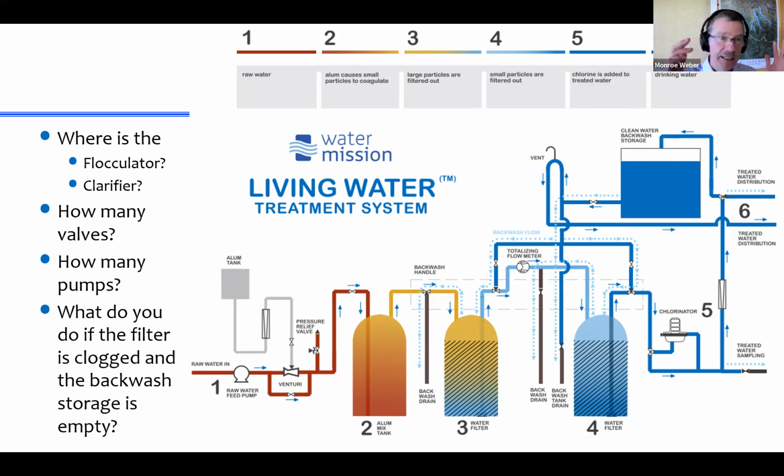It enters the entrance tank. It goes through the LFOM, into the flocculator, into the clarifier, into the inlet box for the filter, down into the filter, up out of the filter and into the outlet box, and onto the distribution system, and it's never gone through a single valve. Isn't that interesting? There are no valves in the path of water through an Agua Clara plant. There is an air valve that's opened and closed when you want to do the backwash, but the water that's leaving the filter doesn't actually go through a valve, even in backwash mode.